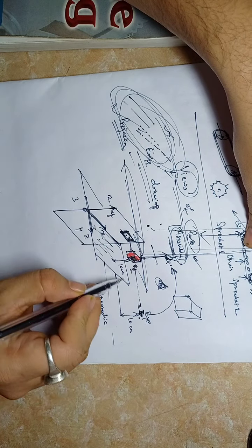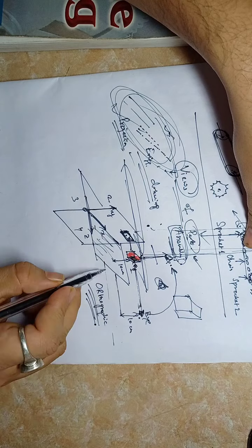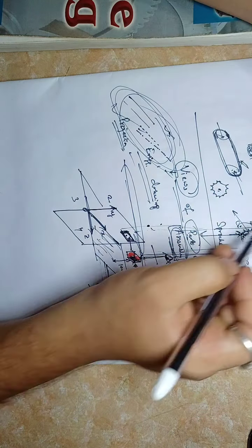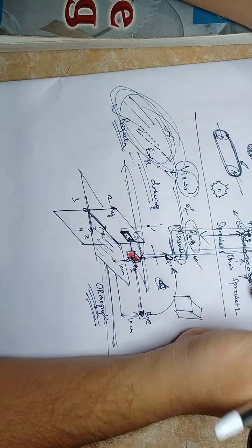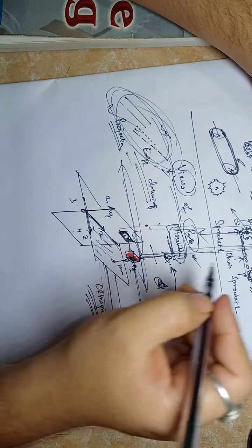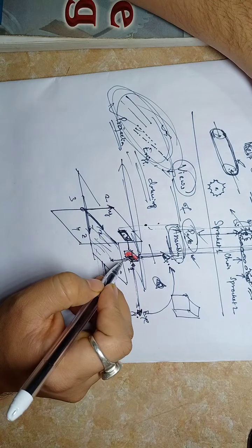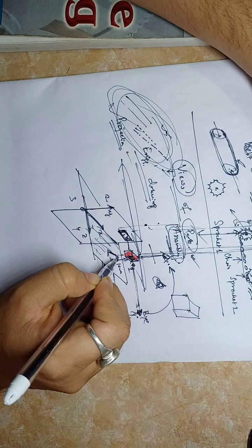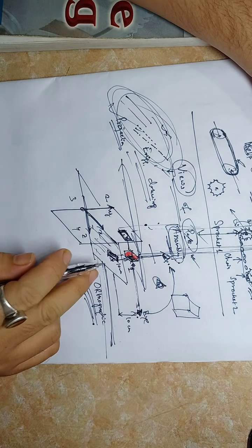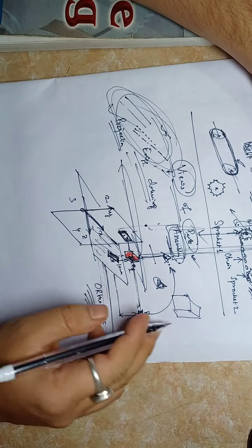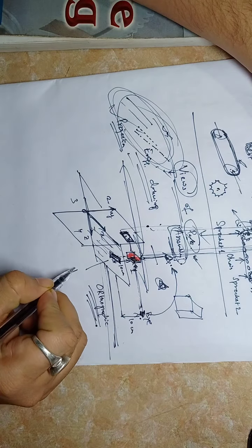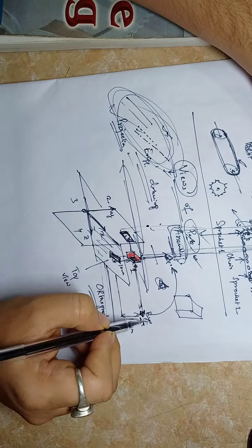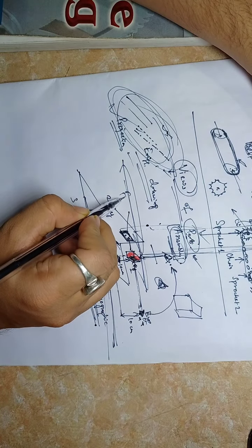In this case it is parallel to this xy plane. Here also the viewing line is parallel to this yz plane. You may be standing at any place, no problem. So if you view from here, the projection will come in this plane, like this. Since you are at the top, this is called top view, and here at this position, this is called your front view.